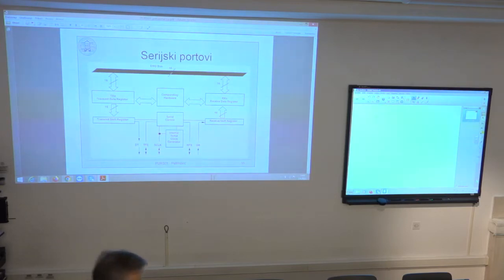And one of those that is commonly supported is I2S, or IIS. It is used for serial communication of audio data, 16-bit, 24-bit, or 32-bit, one channel, two channels, and so on. So this kind of high-quality stereo or multi-channel audio data is transmitted serially over such a serial bus. And you would have this serial bus and a corresponding controller typically on most of those DSPs.